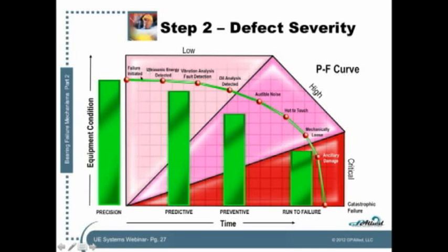When we're in this light pink zone up here, we are at very low severity, meaning the bearing has shown some defect, but in the defect propagation continuum, it's very early, right? And then here, we can start to hear it, it becomes hot to the touch, starts to get mechanically loose, and then down here in zone 3, ancillary damage is occurring. Seals are getting damaged, rotors are getting damaged, housings are getting damaged, that kind of thing, because the bearing is so loose, or because the bearing locks up and starts twisting shafts in half and things of that nature.